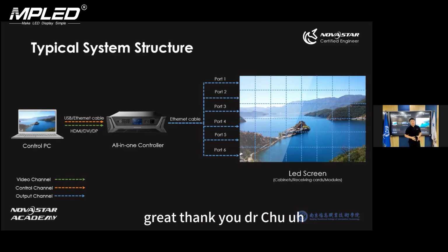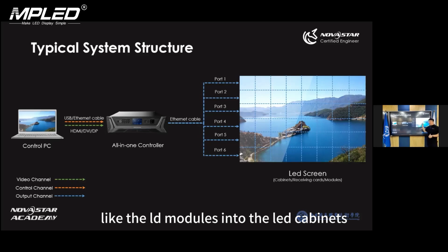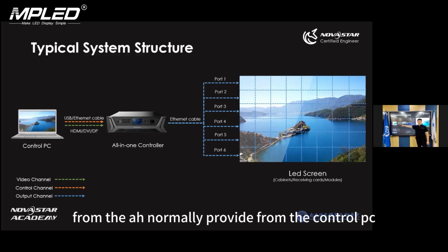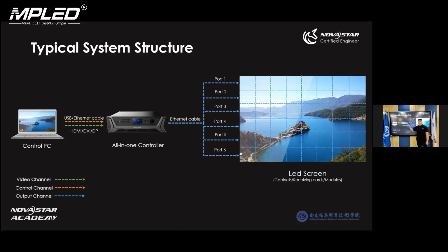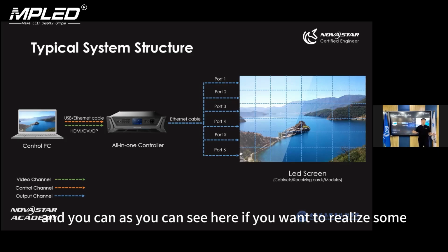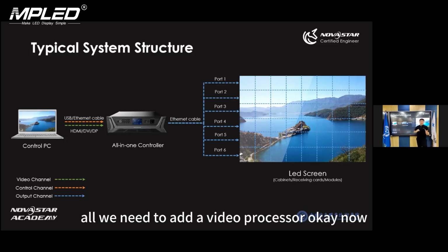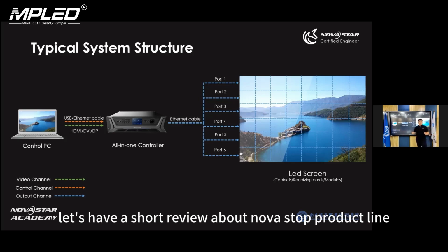Okay, thank you, Dr. Chu. We just learned about the basic structure of the LED control system, from the basic unit, like the LED modules, into the LED cabinets, then to the LED screen. And the video source is normally provided from the control PC, and it will be transmitted to the LED screen via a sending controller. And as you can see here, if you want to realize some basic video processing functions, we need to use an all-in-one controller, right? Or we need to add a video processor. Okay, now let's have a short review of the Novastar product line.